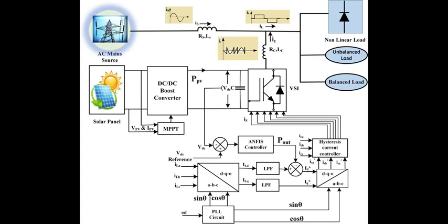Low-pass filters. In certain applications, a low-pass filter may be used to smooth out rapid voltage or current fluctuations and prevent high-frequency components from reaching the grid. High-pass filters. High-pass filters can be used to filter out low-frequency components in the system's output. They are used in specific cases where low-frequency content may need to be removed before the electricity is fed into the grid.